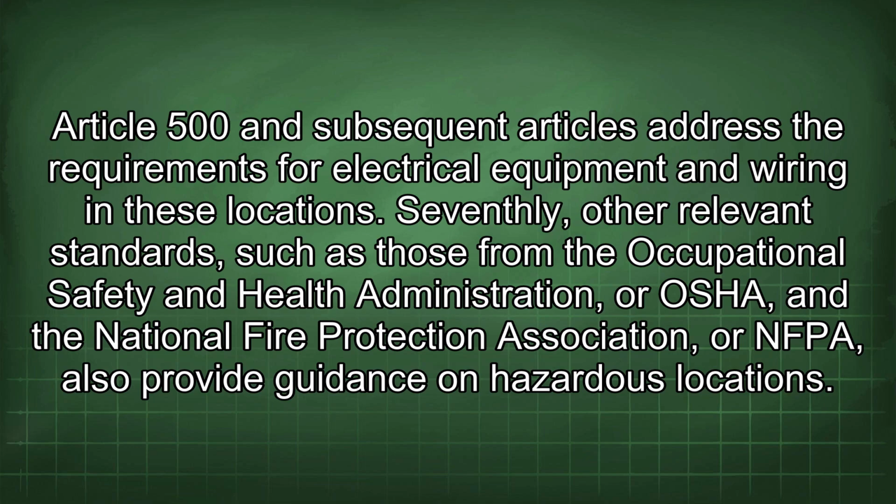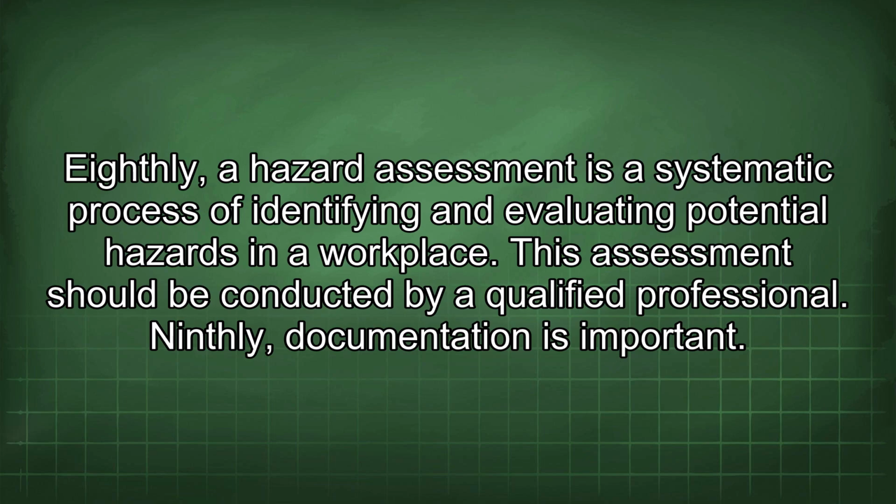Article 500 and subsequent articles address the requirements for electrical equipment and wiring in these locations. Seventhly, other relevant standards such as those from the Occupational Safety and Health Administration, or OSHA, and the National Fire Protection Association, or NFPA, also provide guidance on hazardous locations. Eighthly, a hazard assessment is a systematic process of identifying and evaluating potential hazards in a workplace. This assessment should be conducted by a qualified professional.